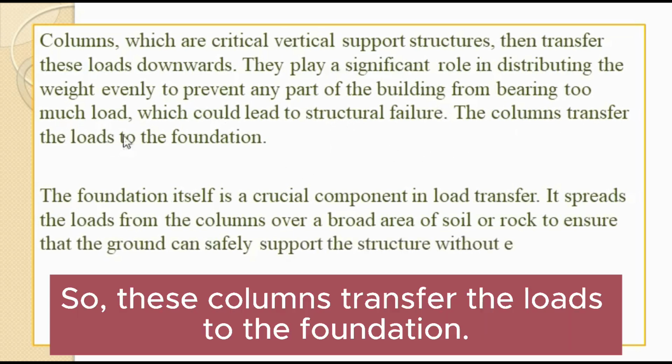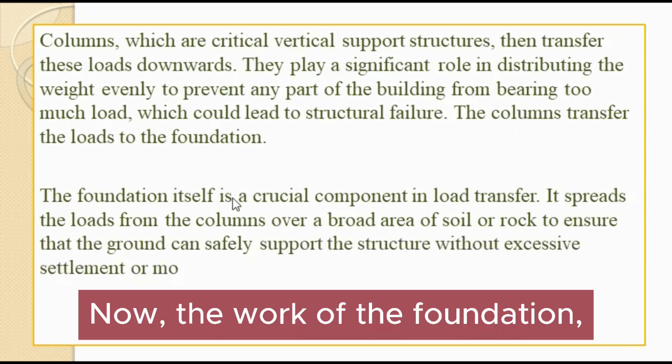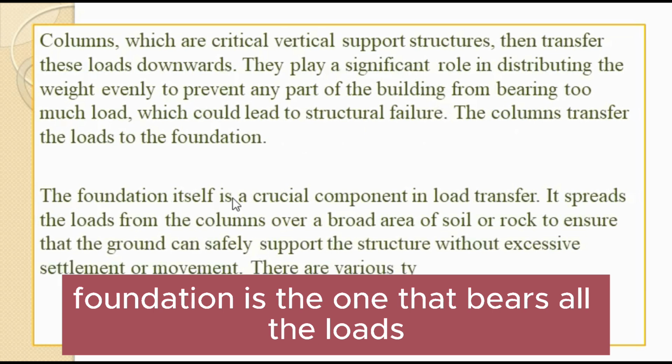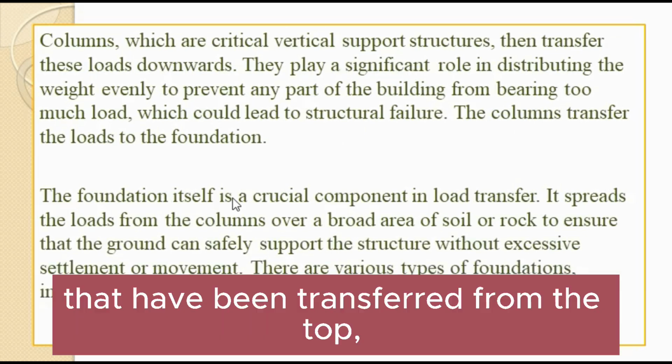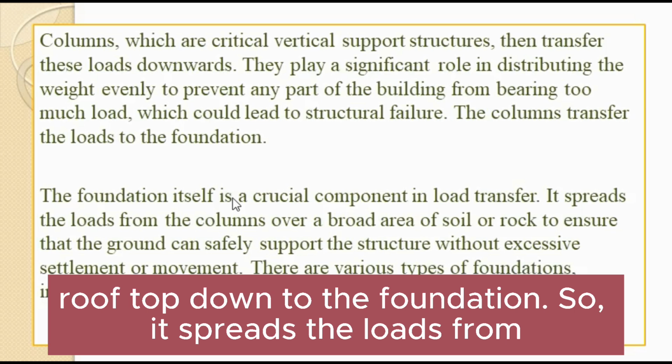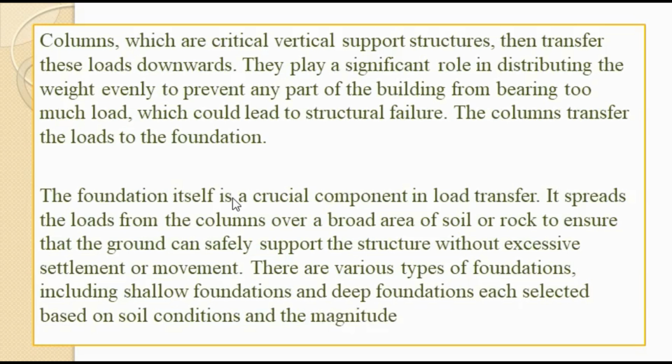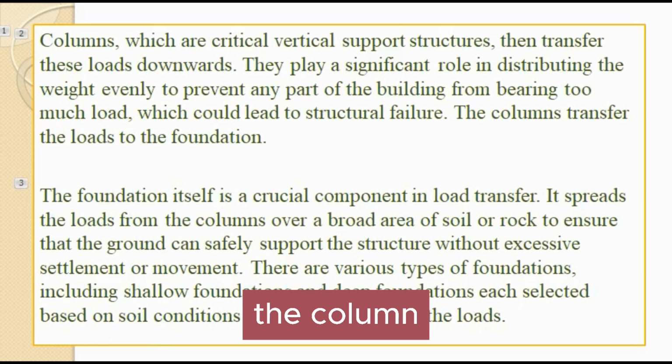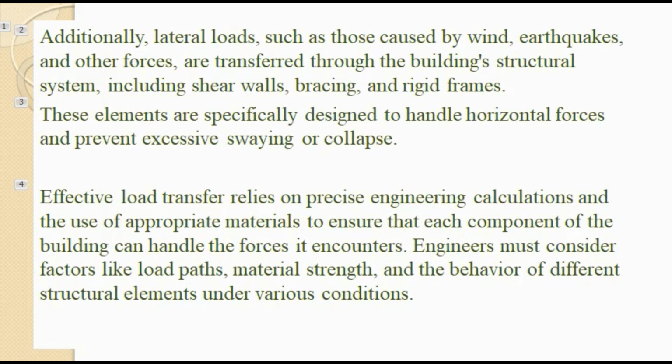So these columns transfer the loads to the foundation. Now the work of the foundation is to bear all the loads that have been transferred from the rooftop down to the foundation. So it spreads the load from the column over a broad area of soil or rock, depending on the type of foundation, whether it is shallow foundation or deep foundation. So it spreads this load and then this load is being dissipated. I hope you are following, you are understanding this integrated process of load transfer and the load path.